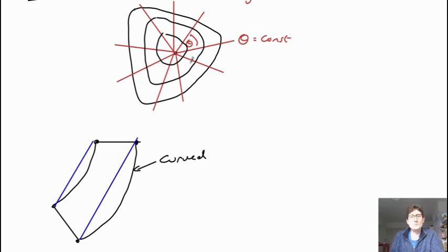And so what will happen is that we choose some cells initially based on this geometric angle. We solve for potential, and what we'll probably find is that the magnetic axis here is not where we thought it would be, so it'll be shifted somewhere, and then we can reuse that to create a new grid, interpolate from the old grid onto the new grid, and then progressively make our grid cells more aligned to the magnetic field.